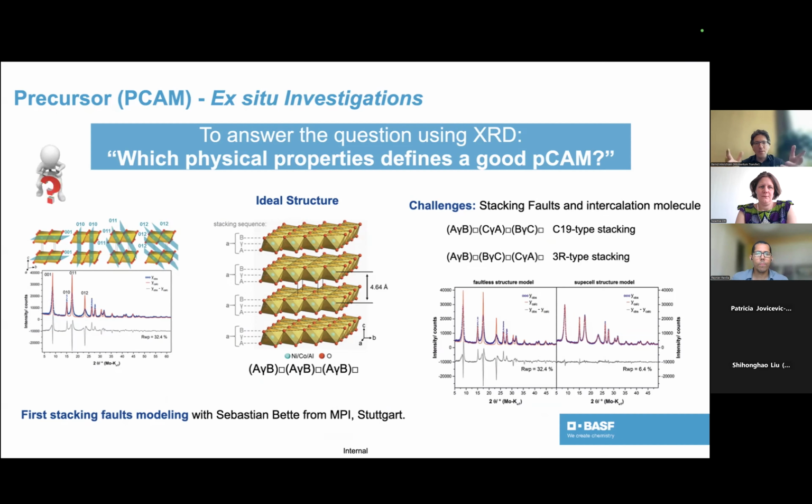Yeah, so what we looked at was the precursor material. What happens is you mix sulfates of the metals as a solution. So the cobalt, nickel, and aluminium sulfates in this case, you just mix them together, and then put it in an ammonia solution. So it's a very high pH, and then you precipitate the materials out, stirring very strongly, so that you put in a lot of energy, and you precipitate out nanoscopic crystallites that are all bunched together into microstructural spheres.